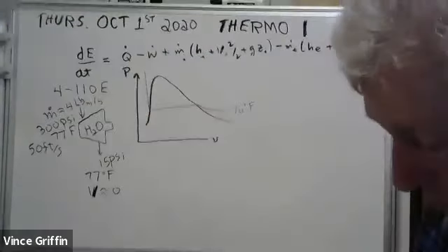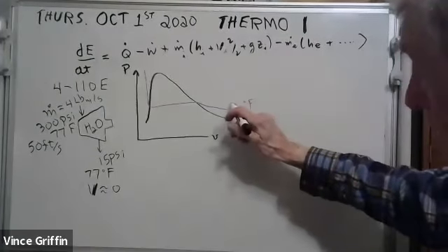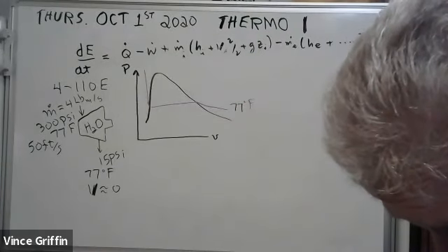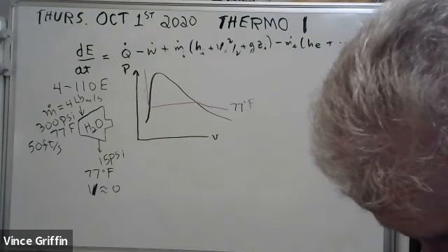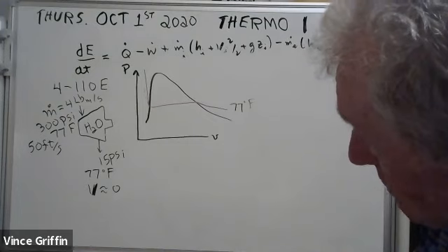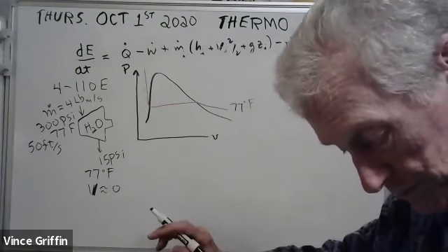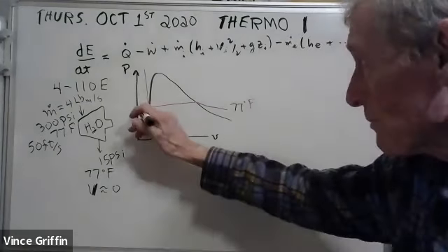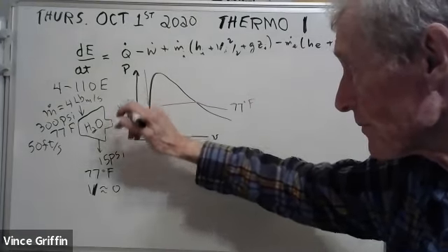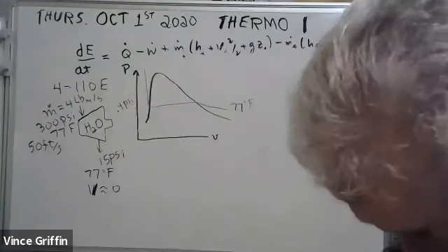I need to know what this saturation temperature is at, no, it's 77 degrees, just a minute, 77. They don't have a 77 degrees, but the pressure is only somewhere around 0.4 psi. I eyeball that. It's somewhere between 0.36 and 0.5.